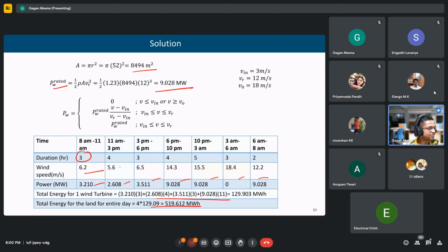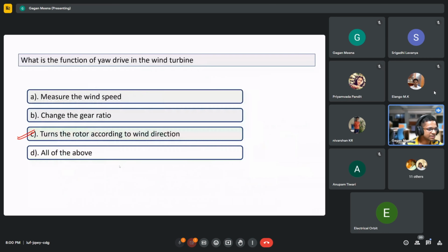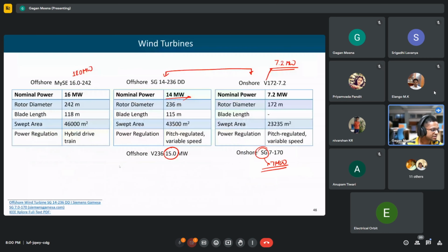They have servo motors for each of the wind blades, and using them they will control it. So automatically they are controlled. It is automatic, a closed loop control. And nowadays they are also using this digital twin technology. So these new turbines, especially the Chinese ones, even Siemens Gamesa, these offshore wind plants which are very high power, are using this digital twin technology.